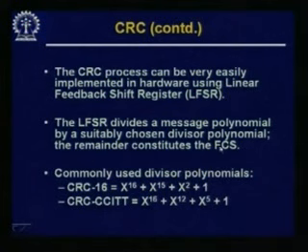As I said, this is the G, the so called generator polynomial. So, G will have 1 in the 16th position, 1 in the 15th position, 1 in the second position, and 1 in the 0th position. Which means that there are going to be 4 ones in this G, and all the rest are going to be 0. By the way, usually for some purpose this is kept as odd, you will find.